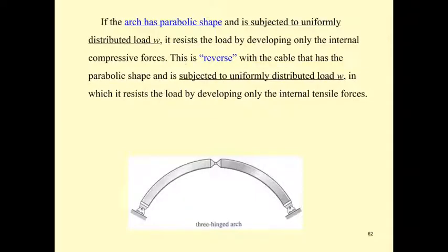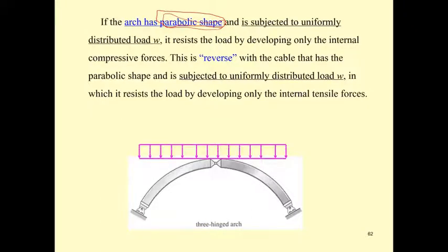And for myself, I like the arch with parabolic shape because it is not too deep, like a circular arch or even the catenary arch. And most of the arches that I see in the bridges in America have a shape like a parabolic arch. We will discuss this later in the example.